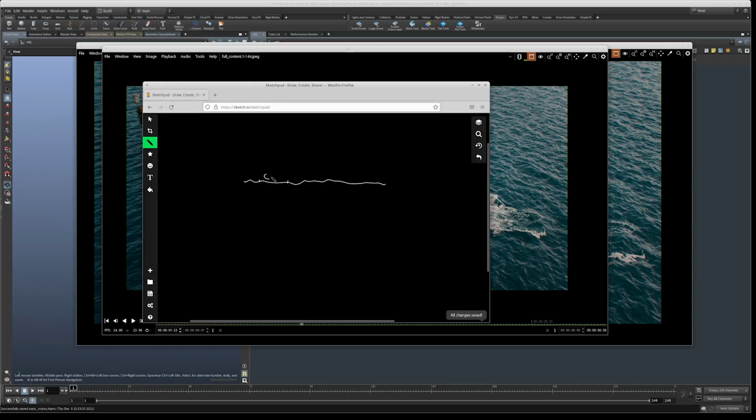So we have a toy here, and this is where the simulation part is going to be. We take that, we put it through the FLIP solver, and then we combine the result back with a grid, with a mesh. So this is the surface, we have the water sim here, and then we sim this part and then combine it and deform everything with the ocean spectrum. That's what the node in Houdini does.